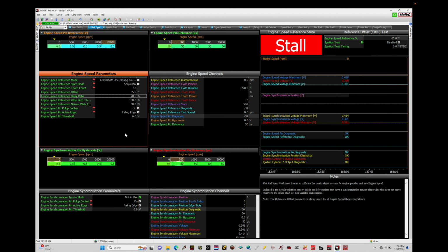Now I've captured ahead of time the engine cranking, the engine running at something like 2,000 RPM, and then the engine running between 4,000 and 5,000 RPM. We're going to need all this information to be able to populate things like our hysteresis tables here. It's very important when we're talking about a Reluctor sensor. Things will make a little bit more sense as we go through the training module.